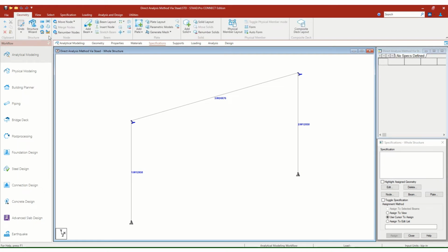Let's go back to geometry. Let's change our units. Now I'm not going to change anything, because just remember I don't have to put in a distributed load or anything like that. So since I don't have to do anything special other than put in axial loads, I can use the force unit of kips.